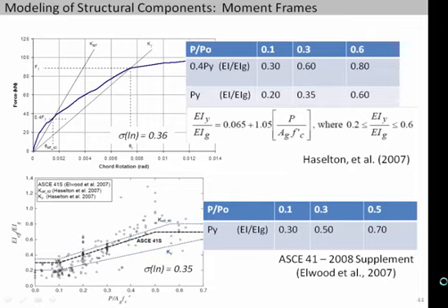But just a key message on effective stiffness is, one, there's a lot of variability in it. You see that in the picture shown below. It's affected, of course, by axial load. But also, whatever we put in as an effective stiffness is essentially a secant stiffness. So it changes whether you're doing a serviceability analysis, where you're not yielding components, versus a nonlinear analysis where you're going to be yielding, where your secant stiffness is up to yield. So much different values, so be aware of that if you're doing analyses with different expected drift or deformation levels.